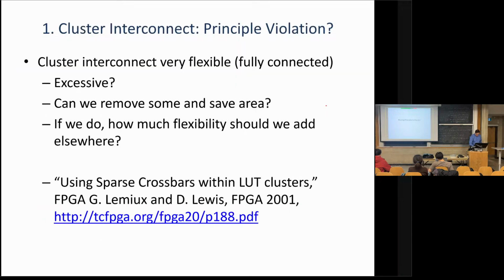Okay, so a few more routing principles, then we'll take a break. I said one of the principles of routing architecture is don't put too much flexibility in one of your routing hops. Every route is essentially a bunch of cascaded decisions. Don't put too much flexibility for any of those because you're wasting area. Don't put too little for any of them because that's going to be your biggest problem.